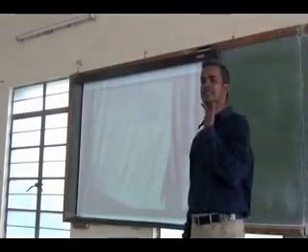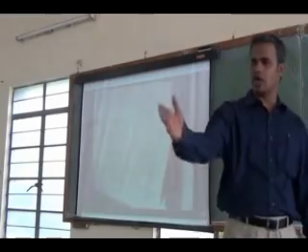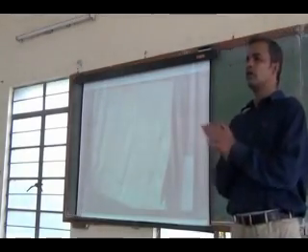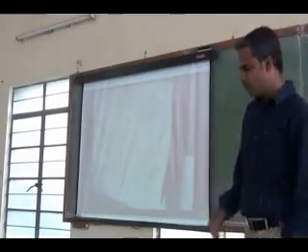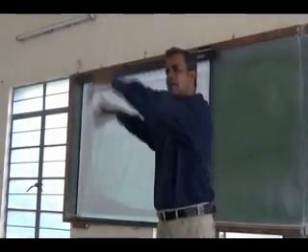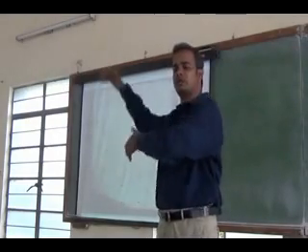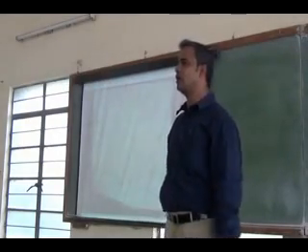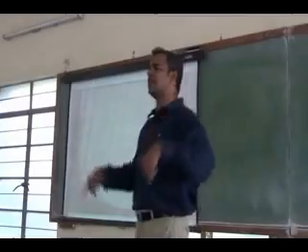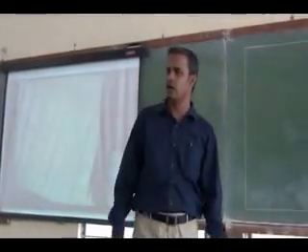And the pencils and all, you can keep it in the drawing table. You have provisions for keeping pencils, your instruments. Right. Is it clear? Fixing of drawing sheets, you have any doubt? You have to fix to the right bottom corner. Okay, the periphery of the drawing sheet has to match with the periphery of the table. Right. With the back sheet, you have to keep your drawing sheet over that which is the drawing sheet. It is filled with the title block and the layout.